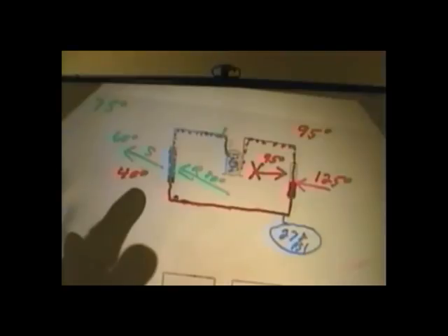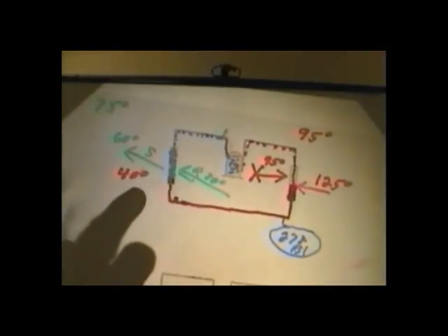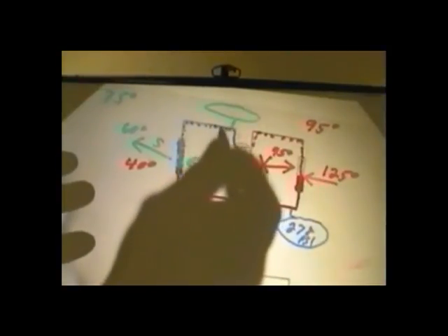How do we know? Just because we said so? Just because I said so and Ray was going to back me up? That doesn't mean it's true. Well, ladies and gentlemen, it's the same way. We're going to take a pressure gauge and put it on our low side, because that's going to measure our low side pressure. And under these conditions, we're going to be measuring about 68 psi.